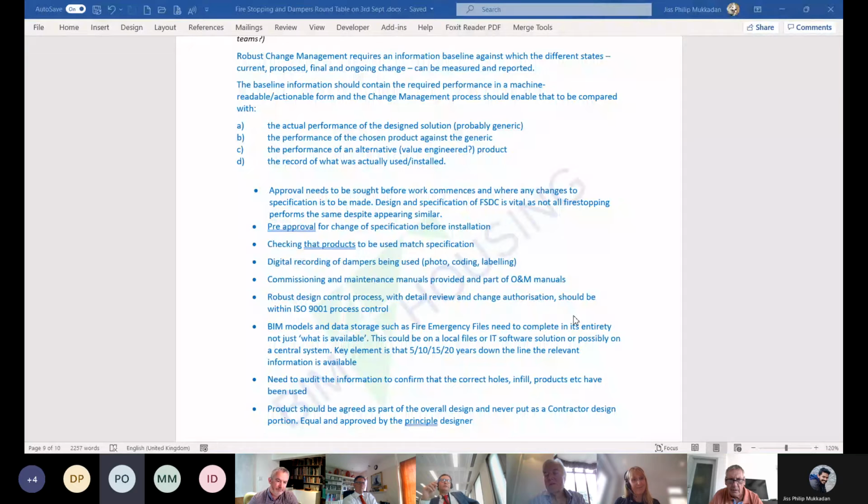I'm sorry. Martin. Oh, sorry. Hi there. Yes, structural engineers should have a full briefing of what they should be designing for. We have this particularly with structural timber buildings, where the deflection of those products can interfere with the fire protection significantly. And it should be very much part of the structural engineer's briefing pack, and they should be taking responsibility.